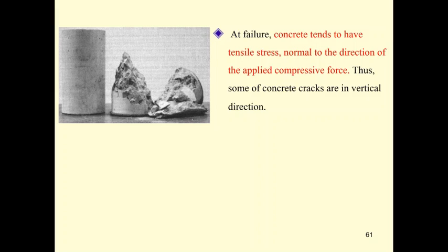Anyway, if you put the force on the timber in the perpendicular direction, you have a timber, and it has this grain, and you put the force here, it's going to have ductile behavior also, because the stress distributes to the wood and to the grain also. The same thing as this one: the stress distributes into the cement paste, and when it's cracked, it distributes into the crushed stone and into the sand.